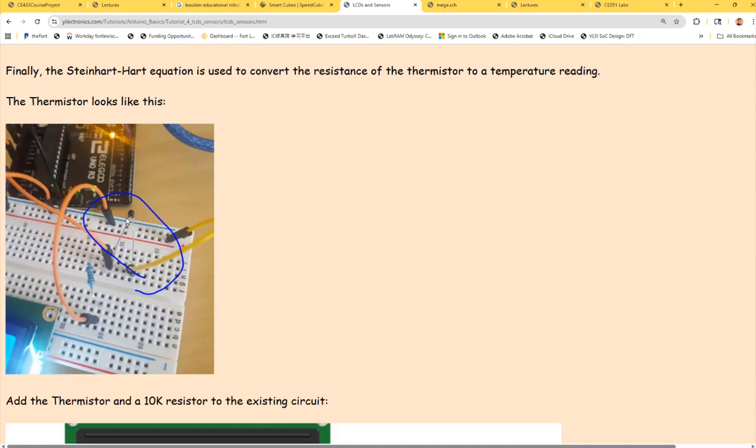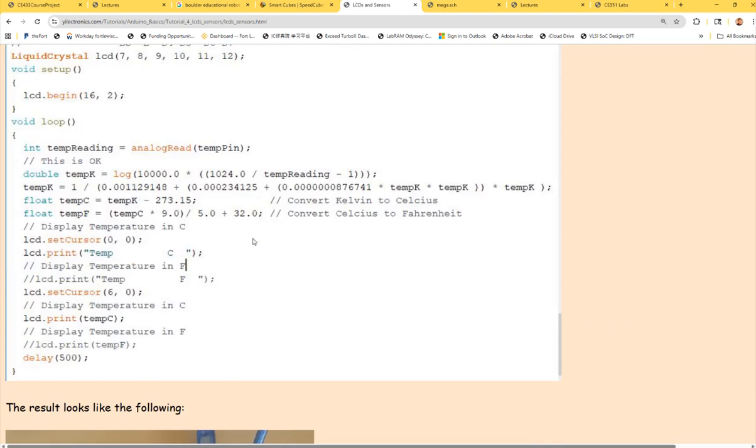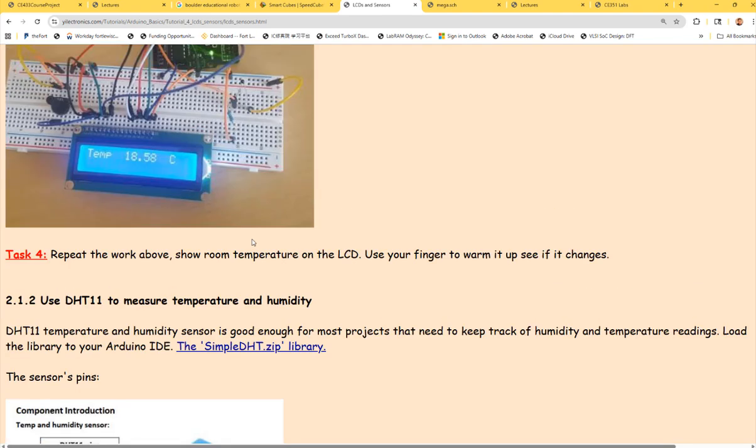And you can do a temperature sensor. I have all different kinds of temperature sensors. It could be a thermistor, which measures temperature by resistance. So temperature changes, resistance changes. You can use a voltage divider to measure it, and the ADC measures the voltage changes and converts them to temperature.